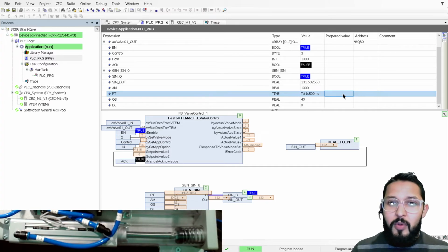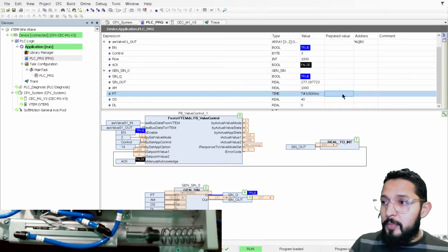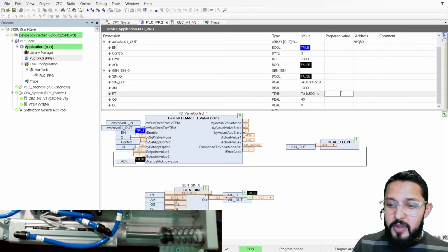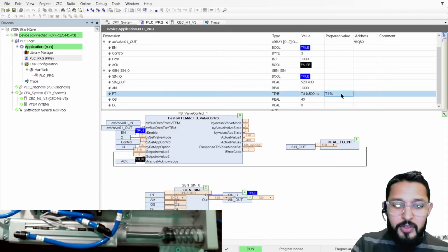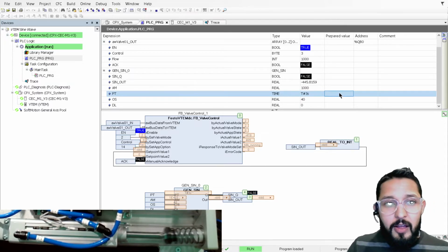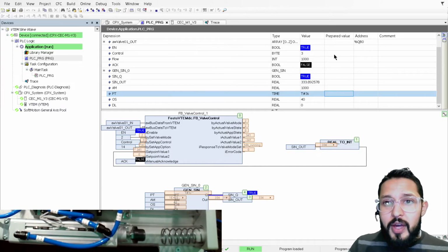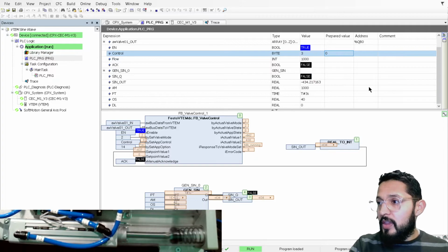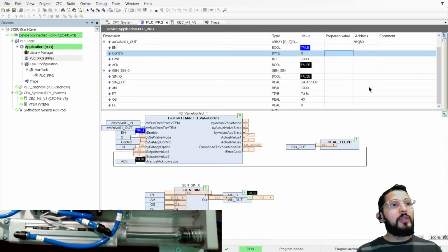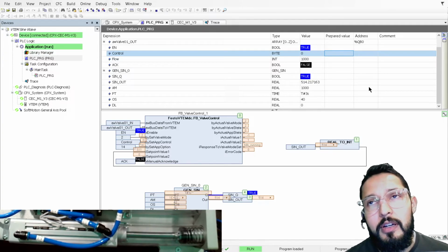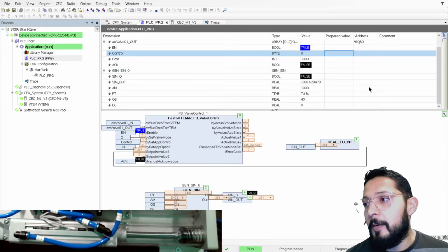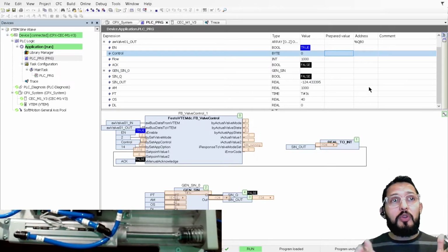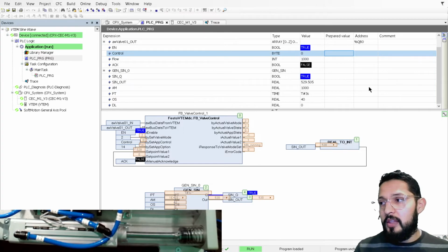Anyways, if I wanted to stop this, for example, let's say I wanted to stop this while it was compressing that spring, how would I do that? I would just set this to 0, which is the control. So I'm going to write that as soon as it's compressing. And now it's going to hold that position because I closed both ports, right? So that's why it does that.